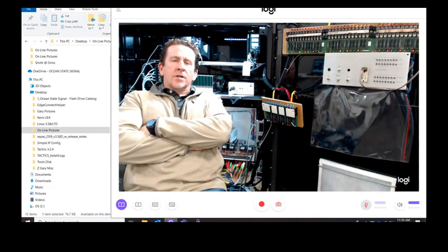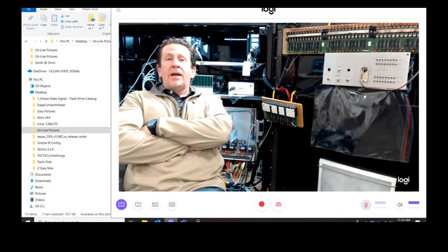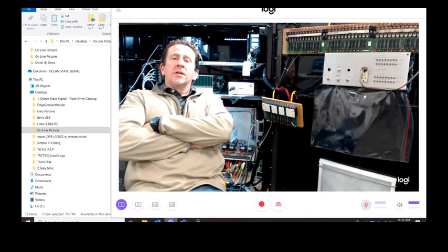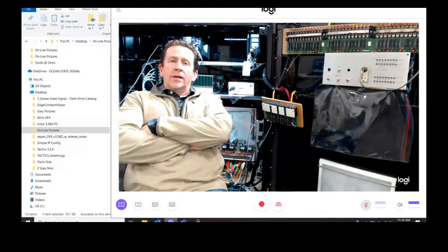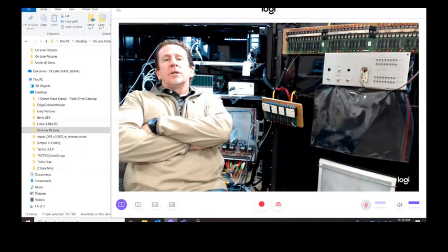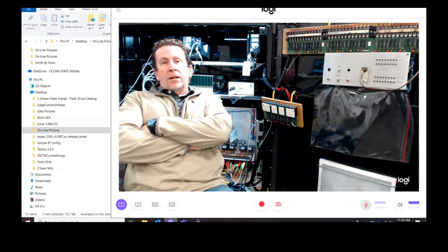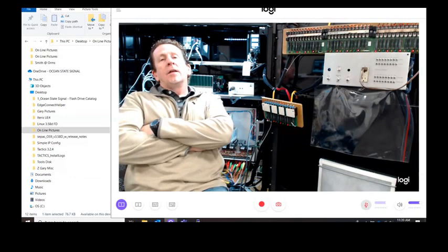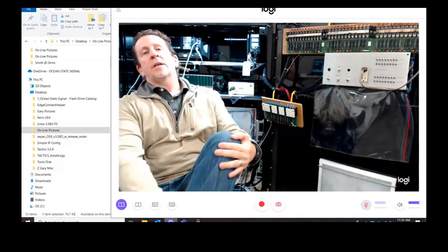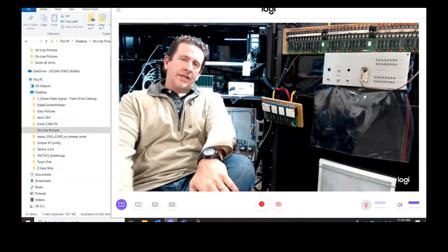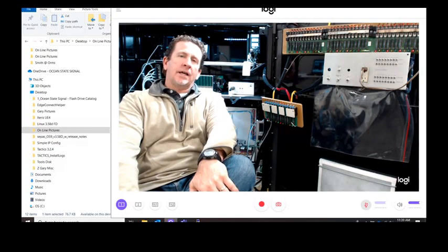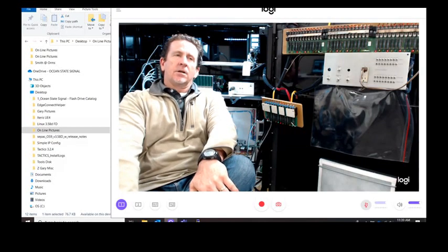And what most commonly happens is a bad yellow LED, typically a bad leaky yellow LED. There's enough load there to satisfy the monitor to keep it going, but not enough when it does the transition from green to yellow to red, so it won't see that 2.7 seconds of yellow time, or that load, that 120 volts, 118 volts on there. So you'll get a yellow clearance fail on that.